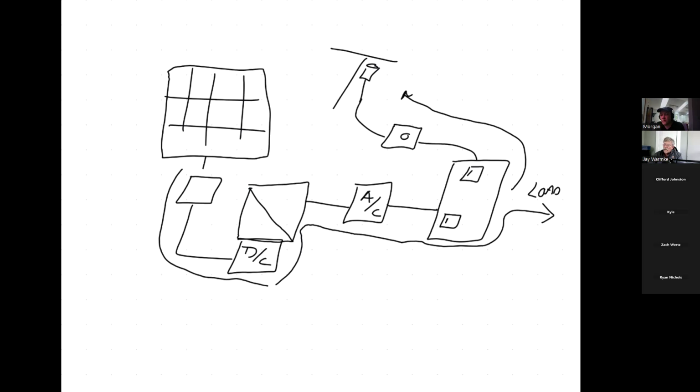So then the grid goes off, boom, comes back on. Well, one big problem is they don't know how much power was being used. Before they did, but now all of these systems that had solar are going to want all of their power from the grid, not just the power they want, less what they're supplying, because their inverters aren't working, right? For that first 5 minutes, those inverters don't work. So the grid might get hit with a lot more demand than they were anticipating. If they do, the voltage is going to drop and the grid's going to crash again, right? So you get this one little flicker.